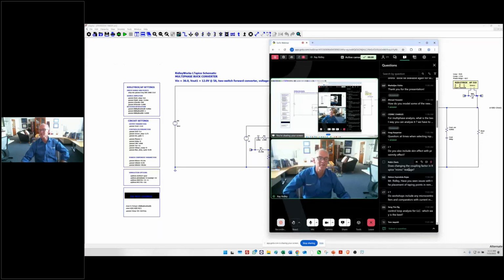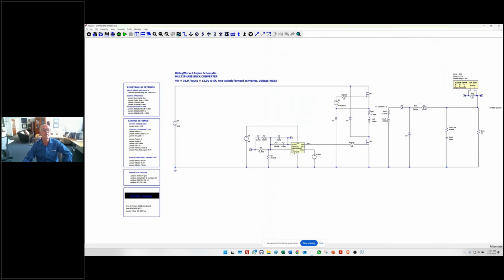I've always thought the leakage was part of it because of that phase shifted full bridge, but it's the first time I tried it. So if you've got this little model here, and you say, okay, I'm not getting the right transfer function out of it, how do we do that? Well, you just grab an inductor, stick it in there. You right click on it, 2 microhenries, done. Okay. Then you sweep the loop. You'll see the damping.